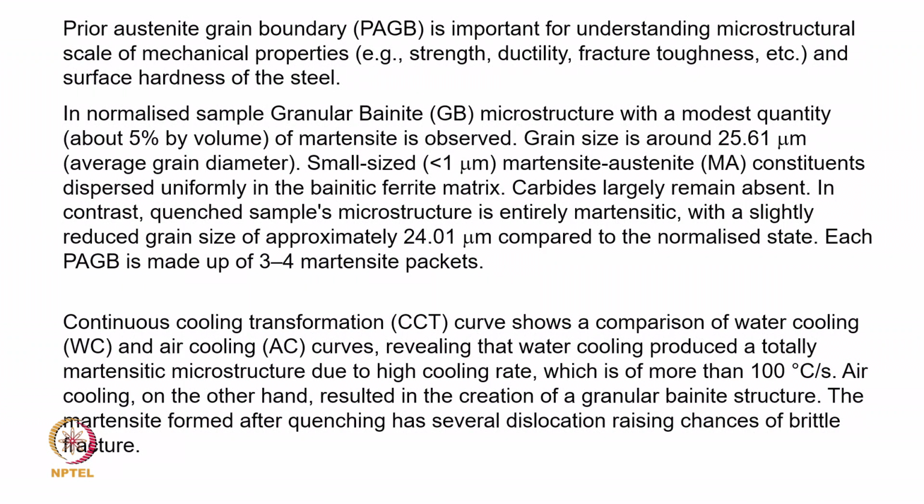Martensite formed after quenching has several dislocations. Another point is that there will be several dislocations, and that will give chances of brittle fracture. So, because of the dislocations, there are more chances of brittle failure. The question comes, so what do we do?